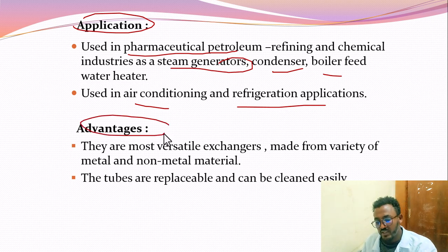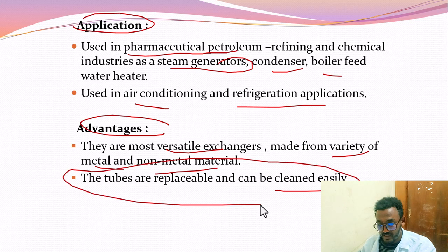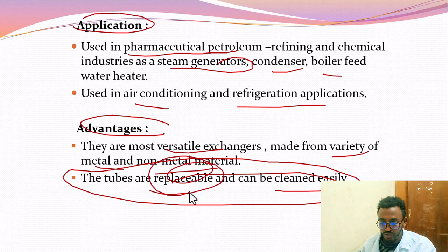If we look at some of the advantages of this kind of heat exchanger, they are the most versatile exchangers, made from a variety of metal and non-metal materials. And the tubes are replaceable and can be easily cleaned. This one is a good point. If you want to, you can easily replace the tubes and you can clean them so easily.